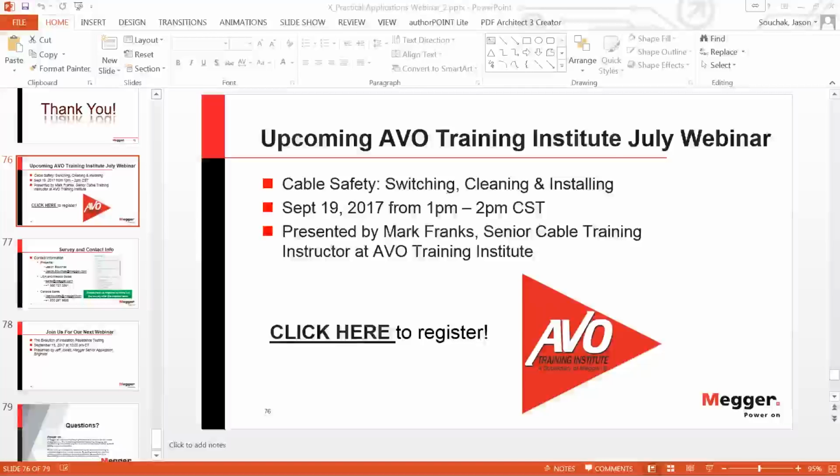That's why the basic rule is you don't want to do any tan delta testing, or for that matter, dielectric testing on cables, before maybe a year where they have been in service and under load, because you start burning some of these components off, and then you get a true tan delta reading. So for fingerprinting, it would not be a good tool. You could use PD testing for fingerprinting, so to speak, on your splices and terminations to see how well that is.